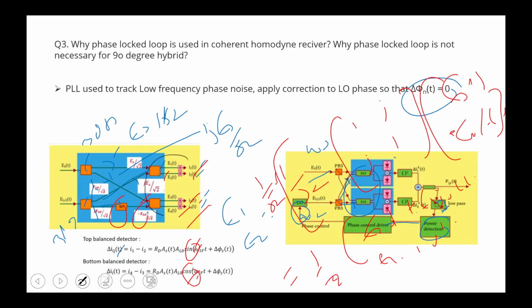So there are two demerits. One is that there is a phase component, phi s, included in this case, and one is the intermediate frequency component. We will have to minimize these through some algorithm. Ma'am has already explained some demo, and some code will be explained showing how you minimize these through the constellation diagram of the QPSK, quadrature phase shift keying, or the 16 QAM diagram. The DSP detection phase of the system, an algorithm chart, will be explained in madam's video. Through that we can correct our constellation diagram.